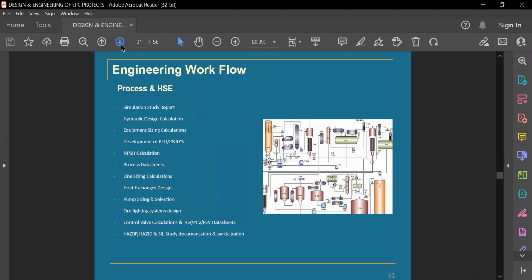And if it becomes high, I'm going to close this valve, I'm going to stop this pump. And in case this valve does not close, then what happens? Then I will say that okay, another valve is there, or another thing is there, or after 10 seconds, if it starts building up the pressure, then I will close the pump. So those are the things. So DCS and ESD will come into the picture, all those things. So these are the things which will be studied over there.